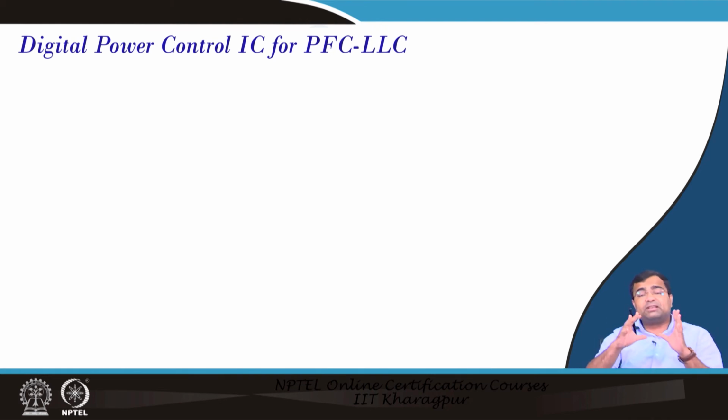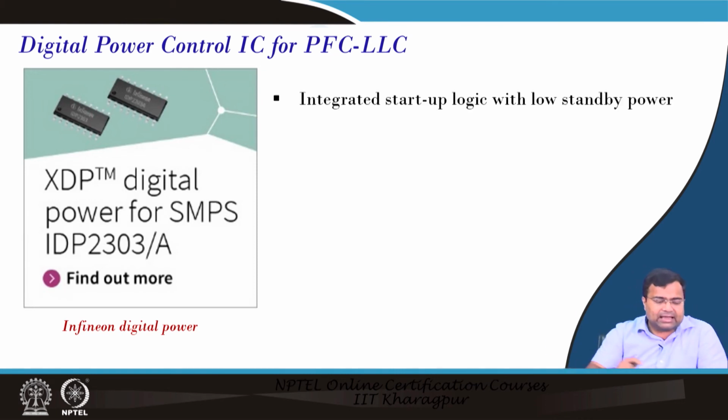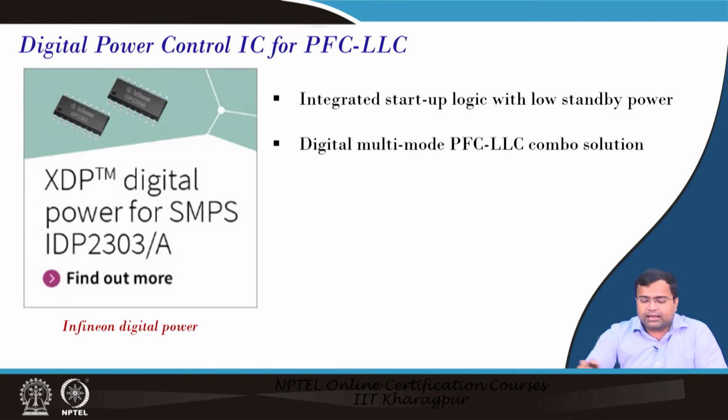Now, so far we have discussed the integrated solution, where either it can be a digital integrated controller or it can be a totally digital power management IC. But now we are talking about another example, the digital controller IC for PFC-LLC, particularly for LED driving application, for display application, and this particular IC actually can control both PFC and LLC together. So, it is a combo solution. It has the integrated startup logic with low standby power, and it uses digital multi-mode control, and it is used for a combo solution of PFC and LLC.